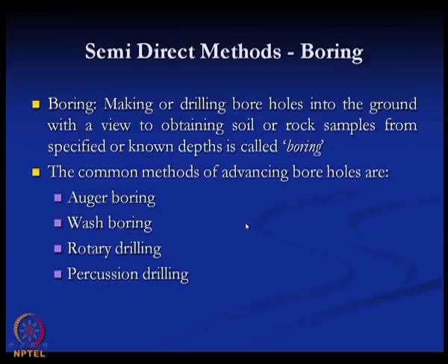Now, semi-direct methods or boring. Boring is making or drilling boreholes into the ground with a view to obtaining soil or rock samples from a specified or known depth. The common methods of boring are auger boring, wash boring, rotary drilling and percussion drilling.